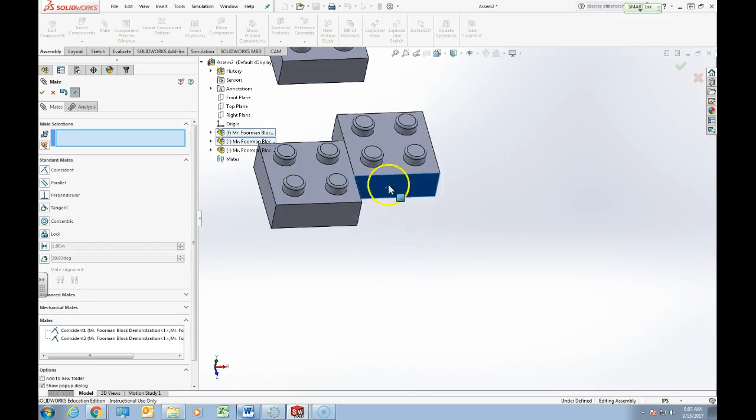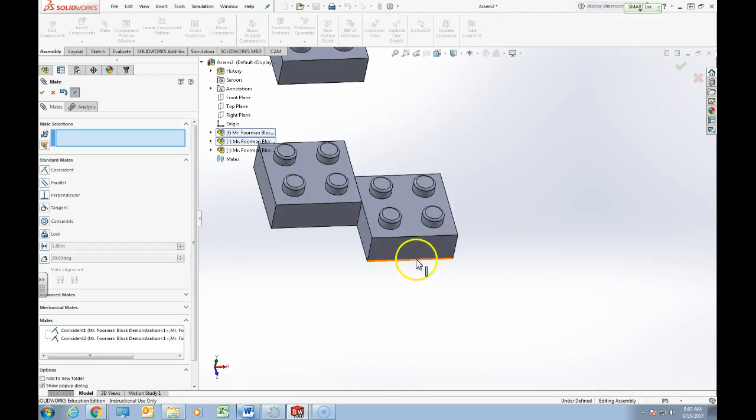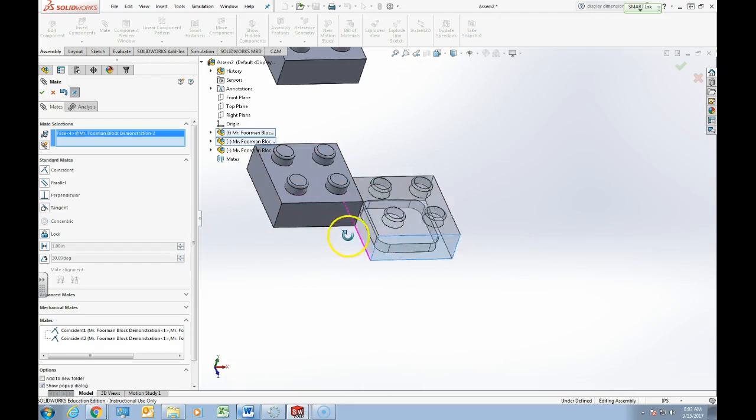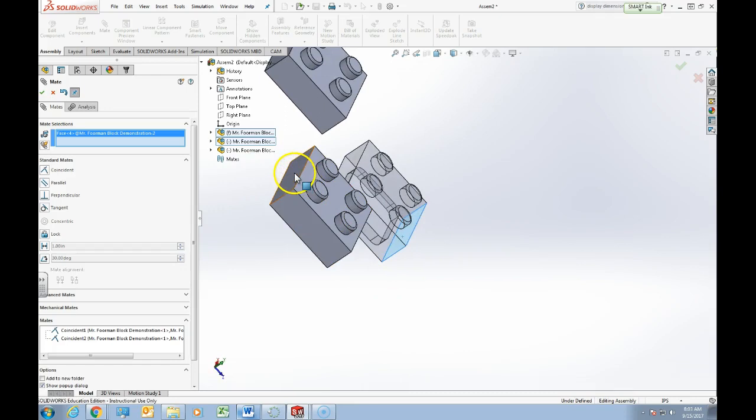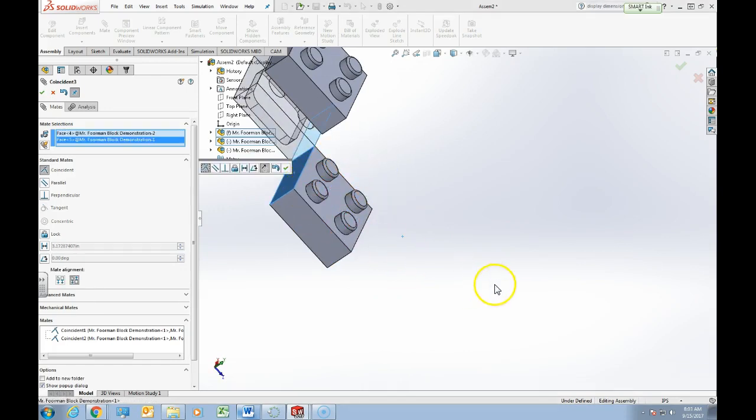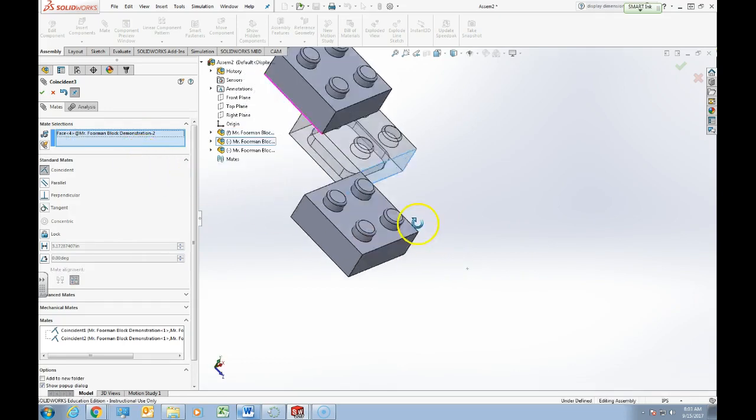Yes, that makes sense. I can only move back and forth this way. Well, how am I going to keep it going? Well, I'd click on that face to that face, right? Well, what if I make a mistake here and I do that and I accidentally click on that face? Oops. Okay, didn't want that. You can just come back here. If you highlight over these things, it's going to show you which face you're actually talking about. It's a subtle change of blue. So it's actually this face. I can come back and then just delete that selection, okay? Didn't want that.